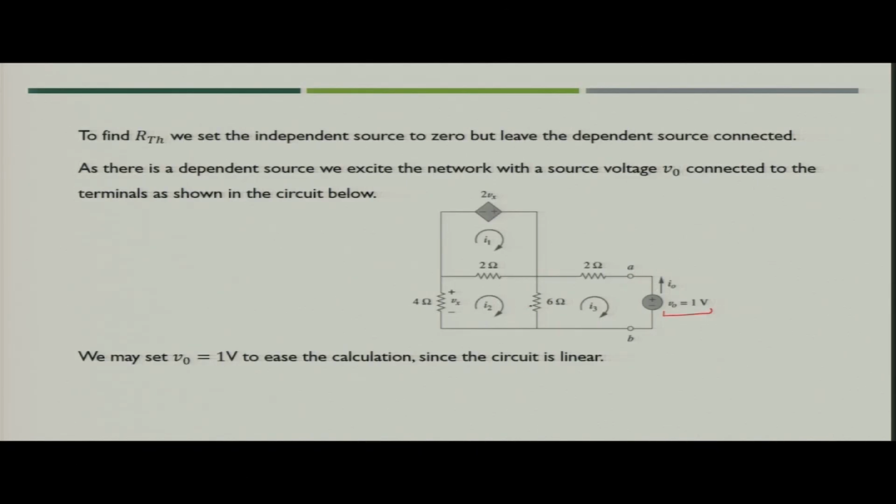So, here we have made the current source as open circuit, which was connected across 4 ohm resistance, and additionally we have added one voltage source across terminal AB, that is V naught is equal to 1 V. So, the updated circuit is as shown in the figure. Then you will see how you will solve. You can use mesh analysis, which we discussed earlier. So, here we have 3 meshes connected. So, we will have 3 mesh currents like I1, I2 and I3.